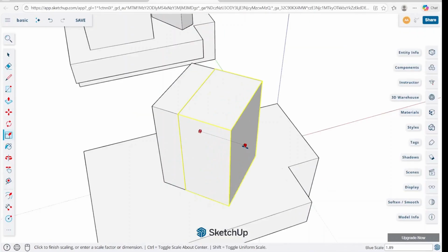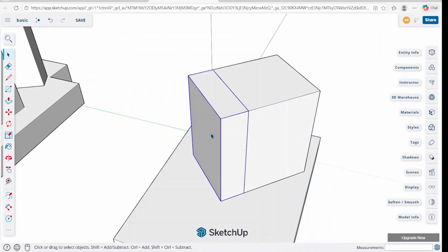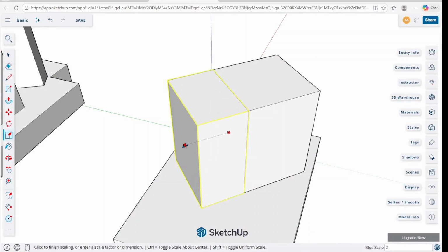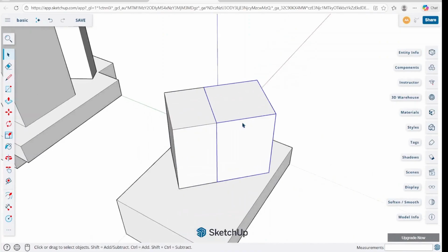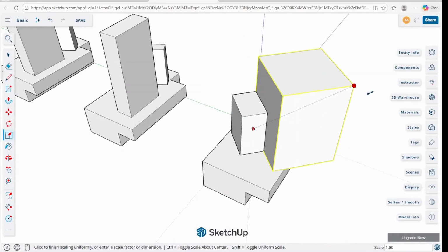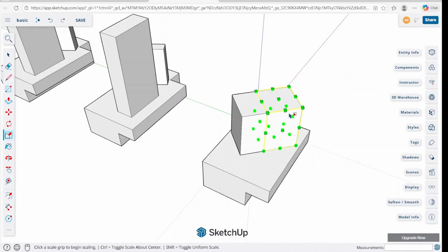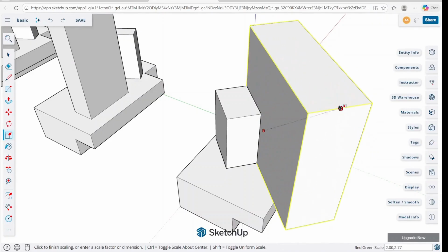Scale command is for changing the size of the object freely or by scale as 2 for double the size or -1 for flipping the object direction. Notice where you handle the object for scaling, results to a different resizing.